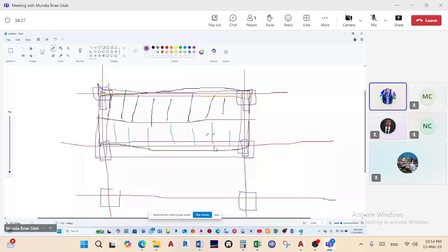Okay, so you have play when it comes to these beams. You are able to make them wider because you have 400. You see, the column is longer in this direction. So you can do 400 maybe by 500, and this is satisfiable. But in this case, because of your column size, you're only allowed to do 200. That's why you had to cut this in half and put another column here. So whatever load will be coming to this beam, divide by 2, half of it goes on this column, half of it goes on this column.